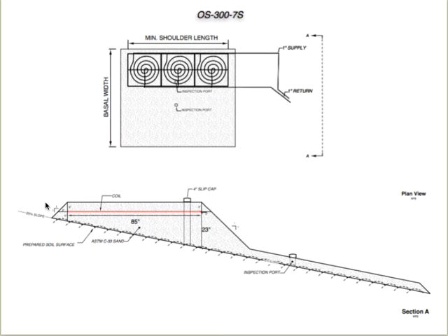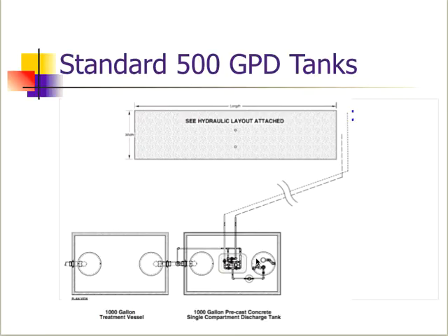And on a sloping site, you'll notice that we've shifted the coils to the upper edge of the basal area. And again, we're maintaining the coils level, so we'll go through a design example to show you how we calculate what additional sand you'll need here depending upon the slope. And then the toe is going to extend out, and again this toe only has to have a minimum of 6 inches of sand on the surface of the basal area.